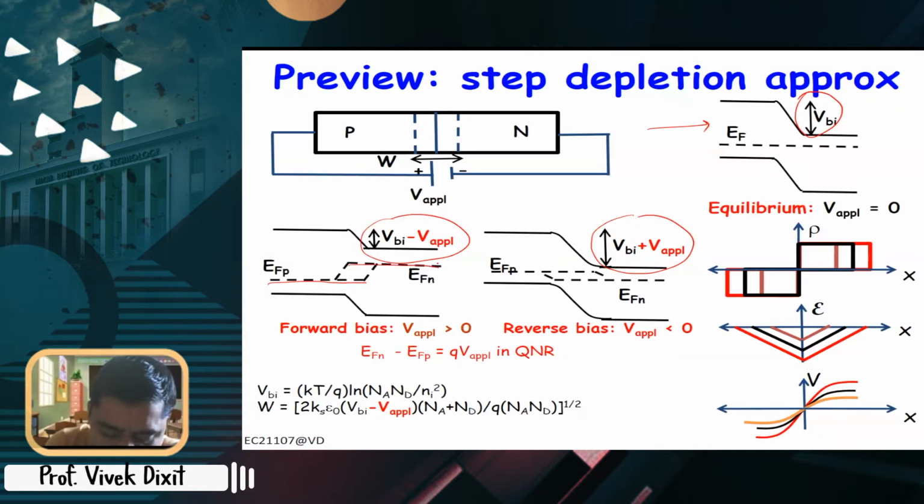and the electron Fermi level, we have two regions here, right? This is called the depletion region, and this is called the neutral region or quasi neutral region. Here there are some fixed charges, so this side will be positive charge, this side will be negative charge due to fixed ions, and these are more or less neutral. Like quasi Fermi level, we have this concept of quasi neutral level also. In case of reverse bias, the depletion width is extended, so your Fermi level is extending here, and electrons and holes have separate Fermi levels.